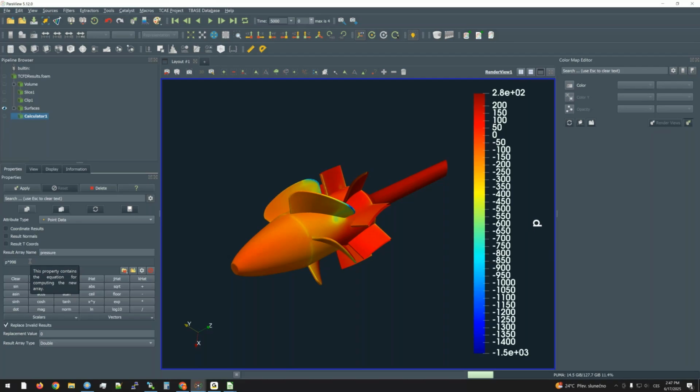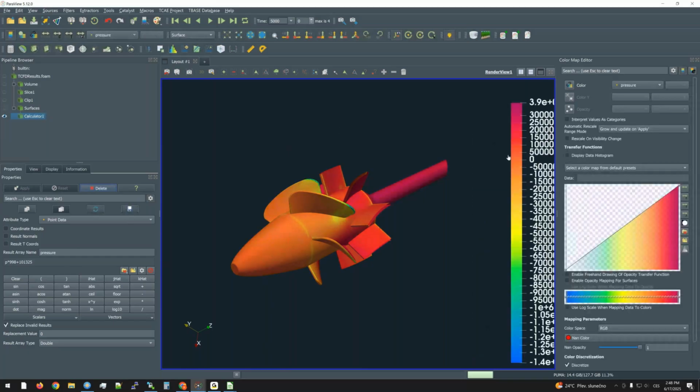So it was density of water which we set. So it was 998 kilograms per cubic meter, of course, and then we would like to add the reference pressure which we set, and the reference pressure was simply the atmospheric pressure. So I'll calculate this.